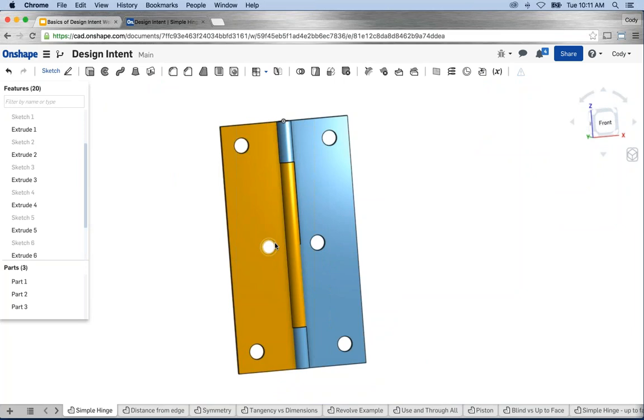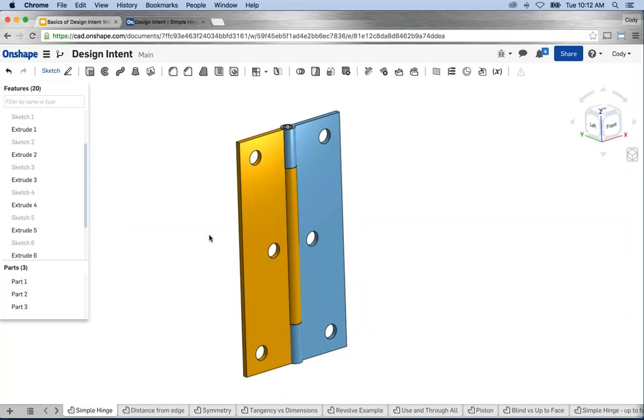And so, important things to point out: the way you dimension things can make a big difference in how it updates and how it handles changes. With a few simple dimension tweaks, I can go from making a design change with 5 or 6 or 10 dimension changes down to 1 or maybe 2. And so it's all a matter of saving time as I go in and update, and getting the correct behavior, the behavior I might expect. Okay. All right, so that's a simple dimension change.